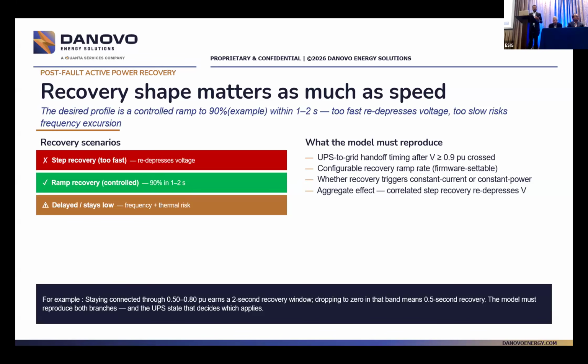And recently, I think the ERCOT requirements had a very interesting edit, right, that showed up, which was, if you are going to be going into momentary cessation, which means that you're still grid connected, but your active power reduces to 0, but there is a battery or any other kind of transfer that's going to start showing up to the grid as a load, you need to be able to reconnect much sooner. And so the 1 second, 2 second requirement that you had is now reduced to 0.5 seconds. Take a look at NOGRR 282 and reach out to Eric.